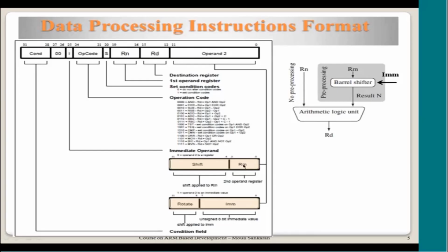Okay, or it could take both things, that is some part of the operand is taken from RM, and then what operation needs to be performed on the contents of RM is provided by the constant, that is it has come with the instruction which is interpreted in a different way, and I will explain to you in the subsequent session here today. So barrel shifter takes this value and accordingly it operates on this RM and then gives the result into ALU.